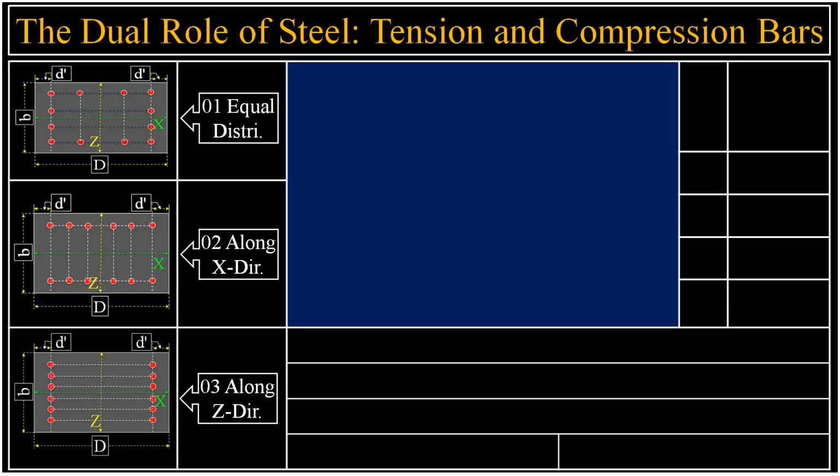Other than these popular arrangements, we can arrange our bars according to the design needs. Primary consideration should be that this distribution must be closer to the periphery of the column, because at the extreme edge of the column, both compressive and tensile stress are maximum.